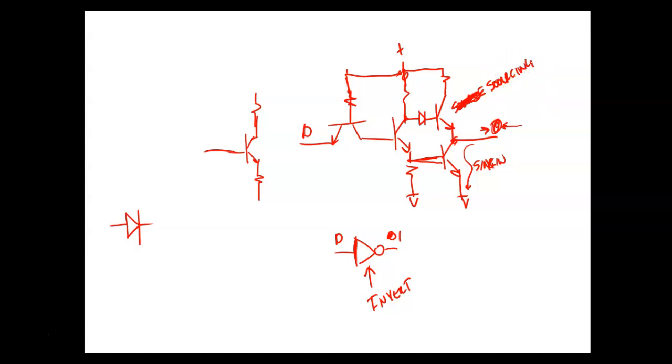So that's what we call these sensors now. We call them what? Sinking and sourcing. So a sourcing sensor uses a positive common, and a sinking one uses the negative common, which is what these guys right here do. So all these IC.